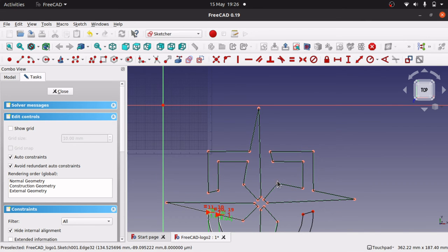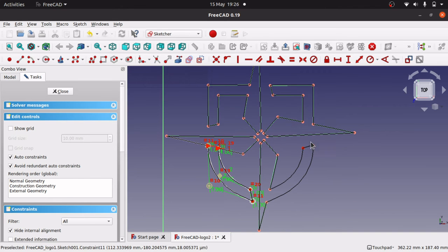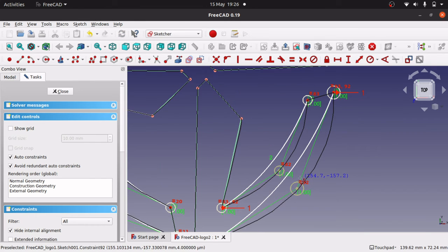So that's all the polylines done. I'm going to come down and finish with the b-spline in here. So this one again is just click somewhere in the middle and click that point there. Hit escape, and we get that line in there. I'm just going to do the other side. Hit escape, and that line's in there, and now I can adjust these two.